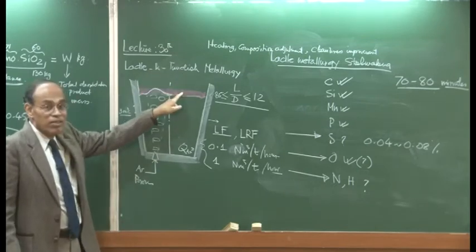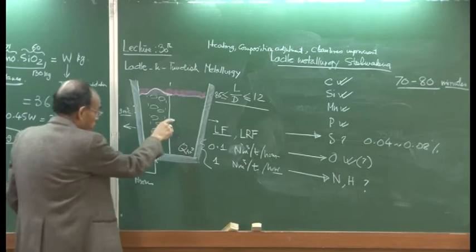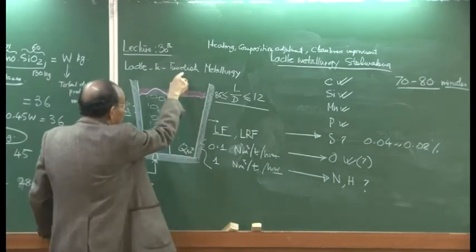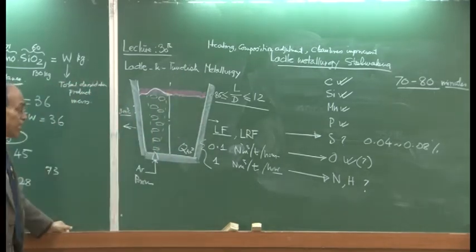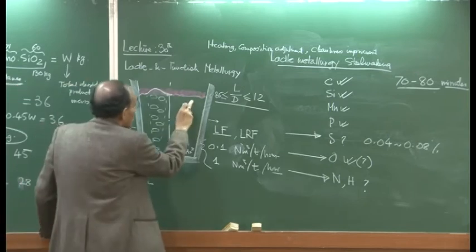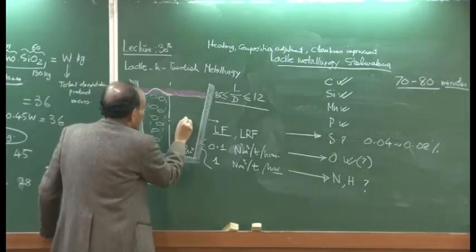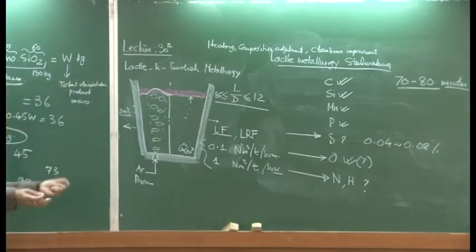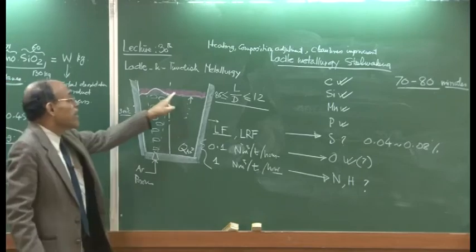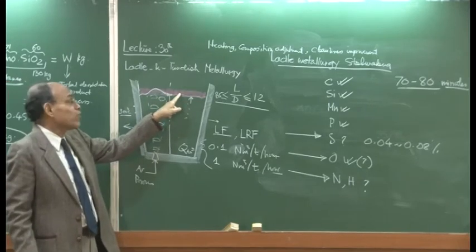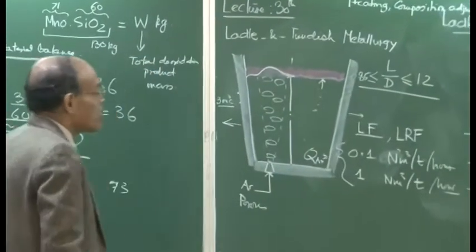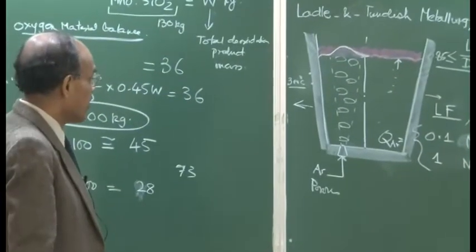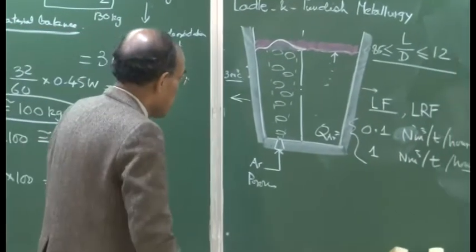The slag will protect the steel from coming in contact with atmospheric air, and also the slag will help to absorb these non-metallic inclusions which are floating up to the free surface. This slag, as I have indicated, will not contain any iron oxide. Carryover slag has to be minimal in order to maximize the performance of ladle metallurgy steel making processes.